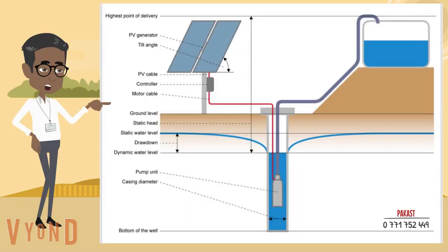Before proceeding with measurements, you need to comprehend what the static and dynamic water level in the borehole is, as well as the height of the water column in the borehole column. The measurement of these parameters is necessary not only for calculating the productivity of the well, but also for the correct choice of a pumping unit for the water supply system.